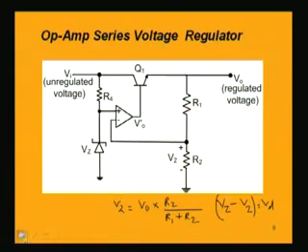So what happens is that V0 dash will now be decreasing, and V0 dash and V0 are almost equal. This is basically an emitter follower, and the output voltage V0 is almost equal to V0 dash, because V0 dash minus VBE is this voltage V0, but VBE is very small, so we can almost say that V0 dash equals V0.